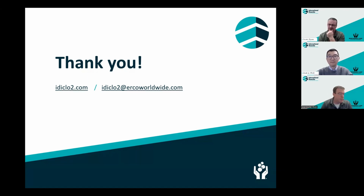Anything to add to that, guys? I would say, if it's a really large water plant, instead of trying to generate enough chlorine dioxide from one generator, it may be beneficial to have multiple smaller generators. That way, if need be, you could put different generators in different locations in the water treatment process. Also, that way you have kind of a backup if one of the systems goes down, that can at least partially treat.